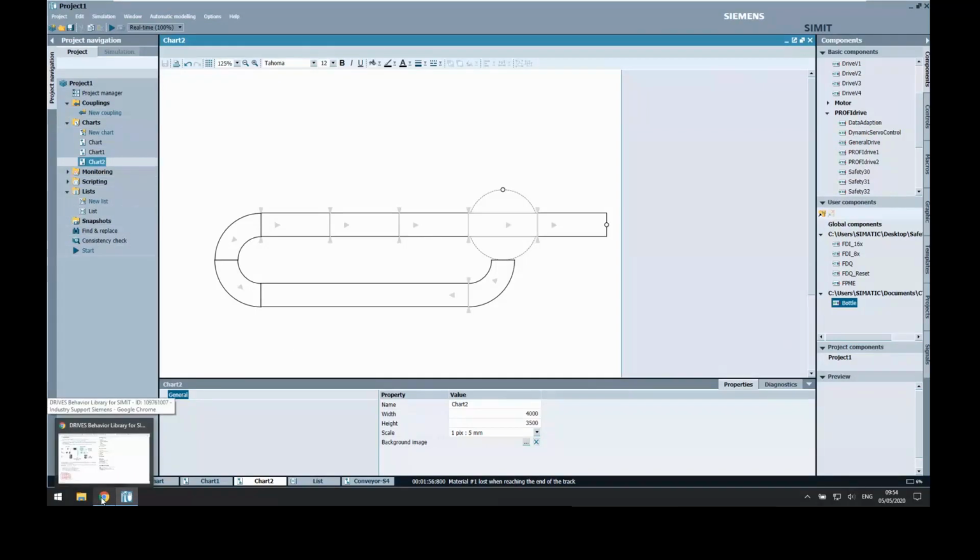Certainly, and I could probably go to SIMIT and type SIOS and type SIMIT RFID for you, but you can do it yourself if you want, and you will find that it is perfectly possible to use RFID technology within SIMIT, and it is actually amazing because you can not only simulate the simple signals going through, SIMIT can actually help you simulate all the information being read and being written. So if you now imagine our bottles and boxes full of bottles, each of these boxes could have a simulated RFID tag attached to this.